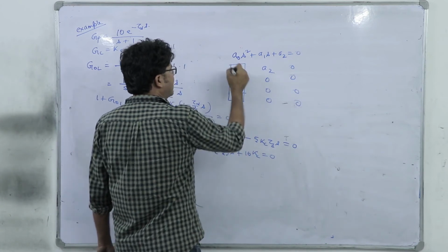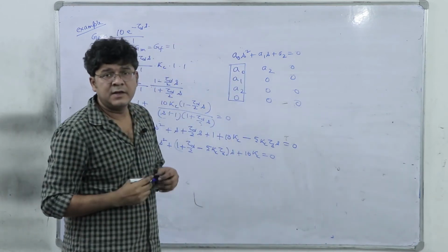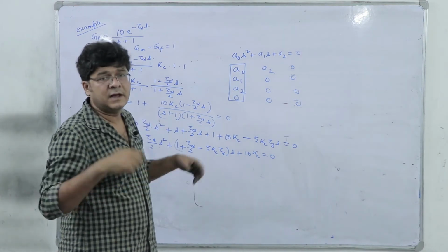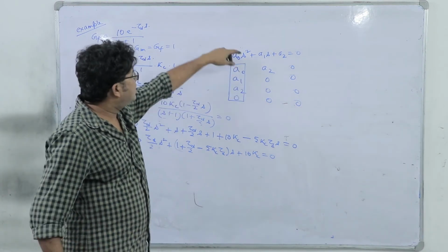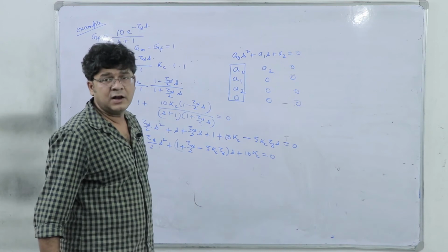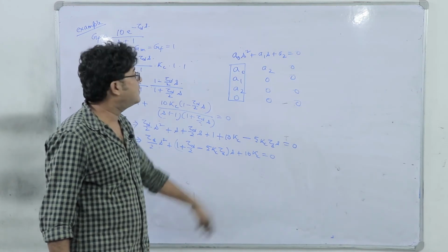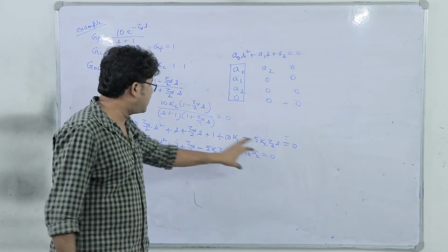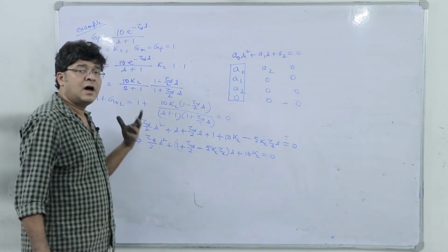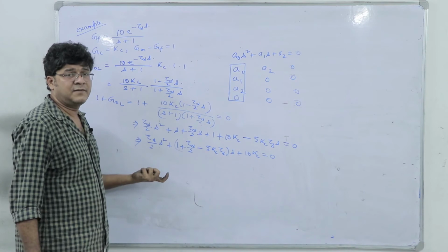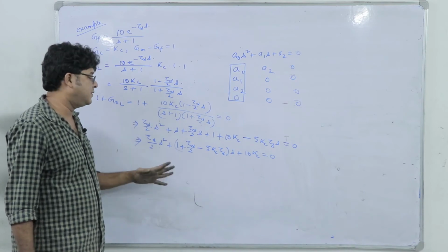So, what are the first column elements? The coefficients itself. So, if I check the coefficients are positive, definitely that is same as checking the first column of the Routh-Hurwitz array to be positive. So, for a quadratic characteristic equation, only the first Routh-Hurwitz criterion is sufficient.